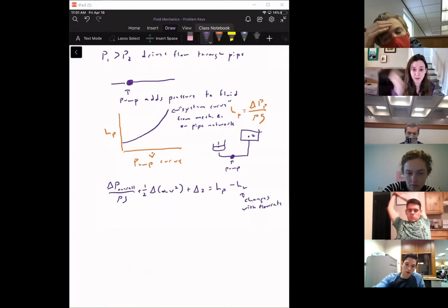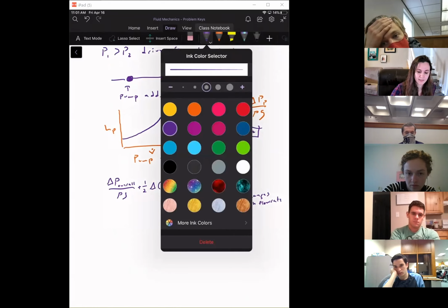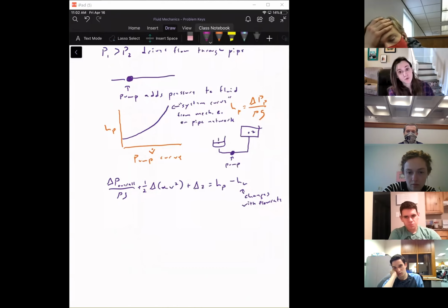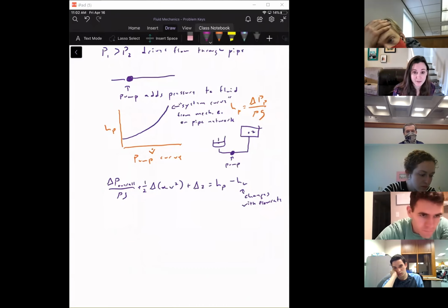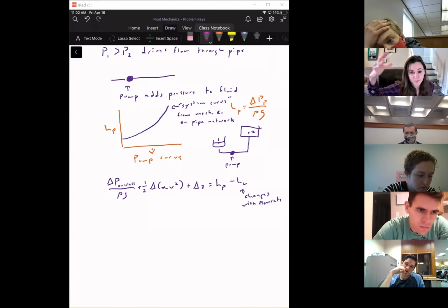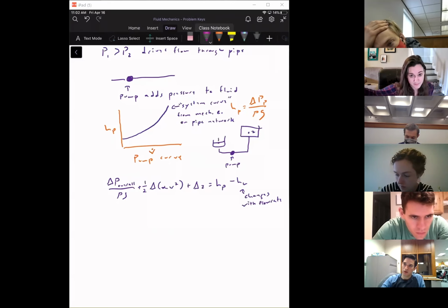So now we think about the pump. That is one of the curves, and then the other curve comes from the pump. We can think about it this way. The pump usually has some kind of shaft that's spinning around, and it's pushing the fluid around and around, and it's adding energy to it. That energy will go into both, but it sort of can either go into increasing the pressure or moving a bigger mass flow rate of the fluid through.